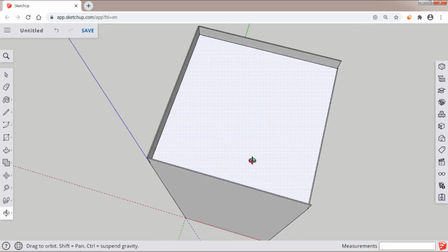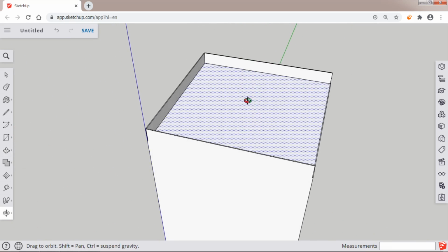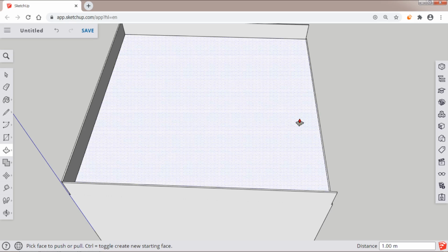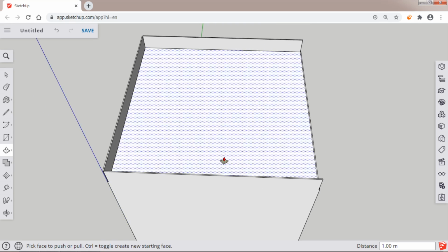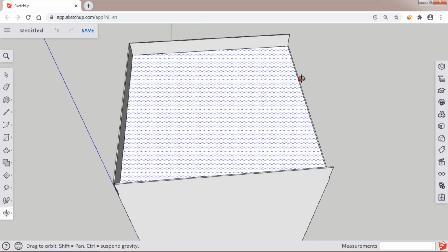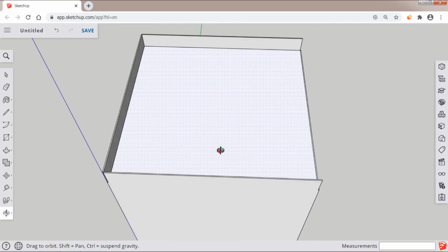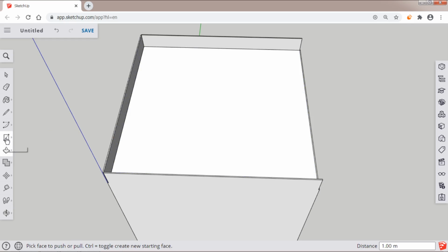The next point is we need to draw the water tank. Once we have done with the water tank, then we will draw the fourth parapet wall. When we observe the parapet wall, it is 1 meter in height and 0.05 meter in thickness. The water tank we will draw from the middle of the line. So again we will select the rectangle command. As we know the overall length of the water tank is 3 meter and width is 1.5 meter.